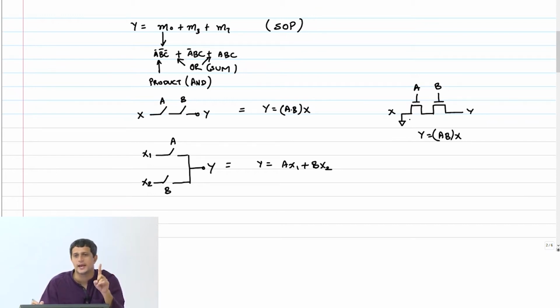And if the signals A and B go high, which means they go to VDD, then both NMOS transistors will turn on. The 0 from here will appear here, and that 0 will also percolate to the output Y. No problem. On the other hand, if I connect this to VDD, then what will go through from here to here is what? VDD minus VT, and further from here to here is also VDD minus VT, right? Whereas for 0, it goes to ground, right?